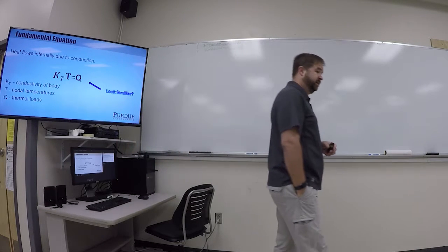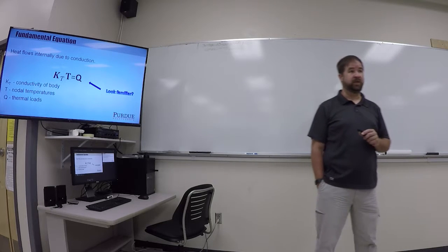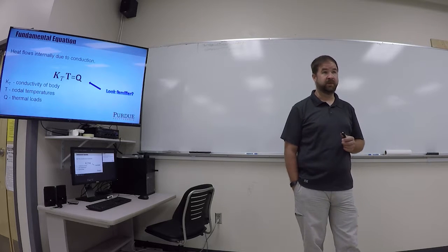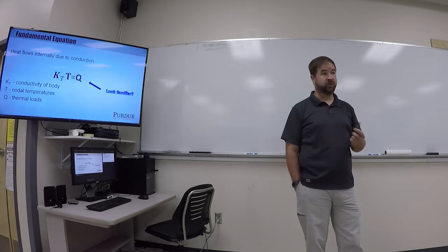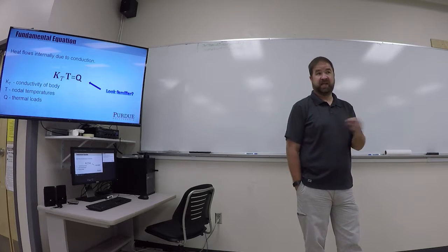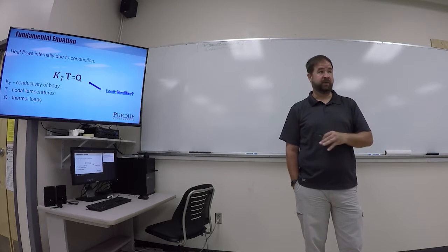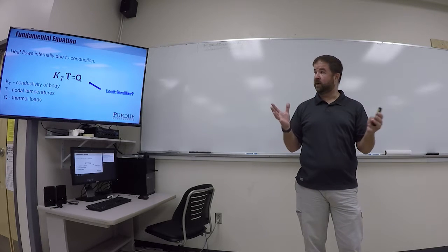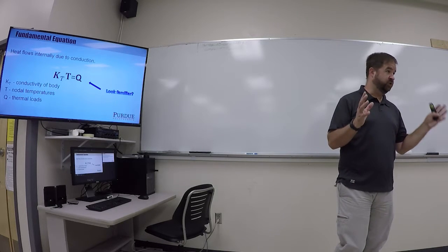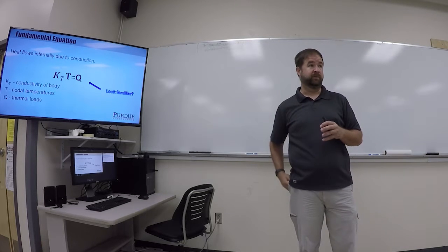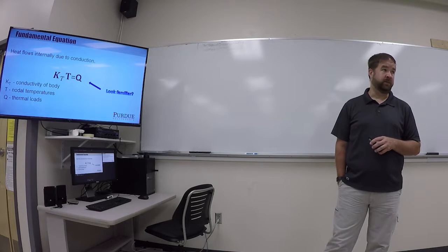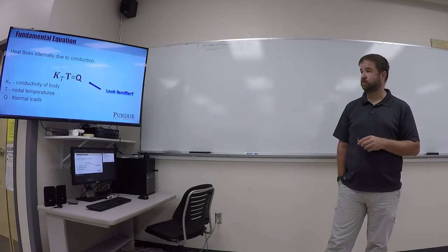So what that means then is I can write a computer program that solves that equation, and if I just put in temperatures instead of displacements, and if I put in thermal loads instead of structural forces, then I can use the same solution algorithms to solve a completely different type of problem. Okay? So that's all this is here. We're using the mathematical framework that's already been generated to solve a different type of problem, a thermal problem instead of a structural problem. Okay? Does that make sense?